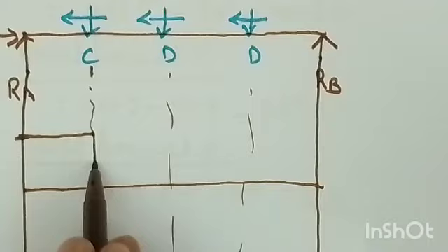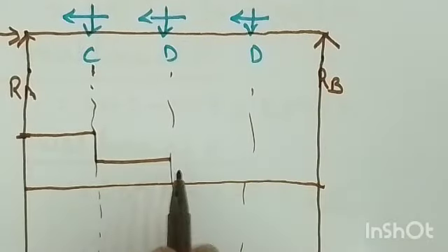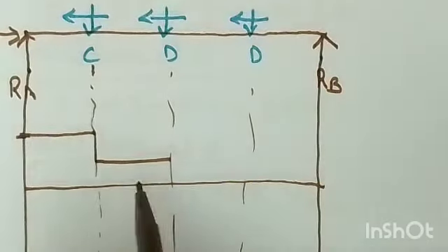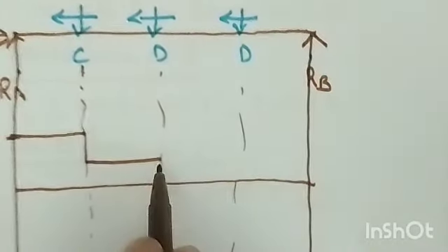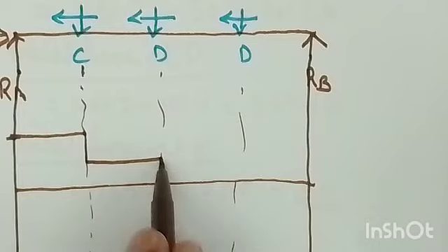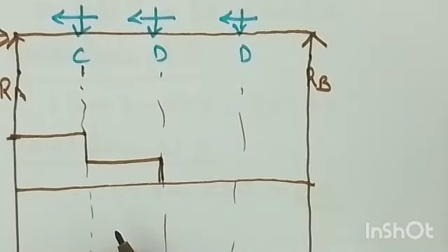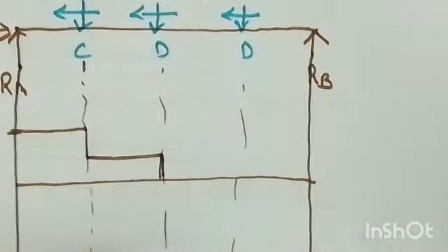Now again it remains constant between C and D, and exactly at D it becomes negative, sorry, at D it is 54.85, right. So at D it is this, right, so it is 54.85. Again, the shear force at D is minus 54.85. So minus 54 means what?